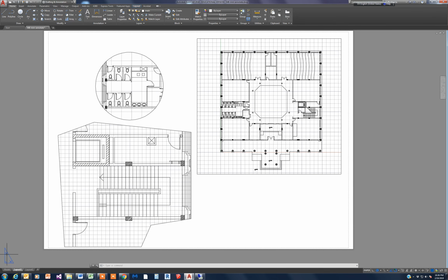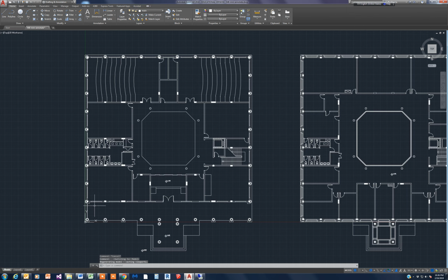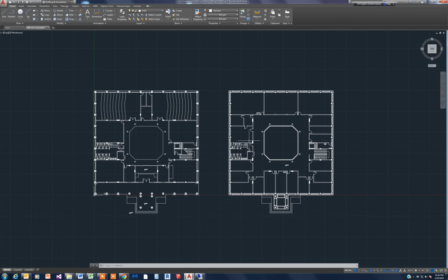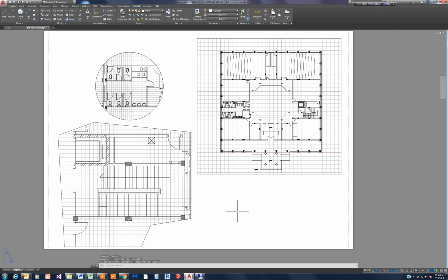Remember, we had this model, two plans, and as I said, don't do any text or hatch and dimension things that are for communication purposes. They should not be here, because once we scale these buildings or any part of it, the text and the dimension will be affected by the scale, and this is not what we want in architecture presentation. You need to have unified text, dimension, and hatching for all plans and details and sections, no matter what the scales are. Yeah? So let's go back to our sheet, which we created last time, A0 sheet.